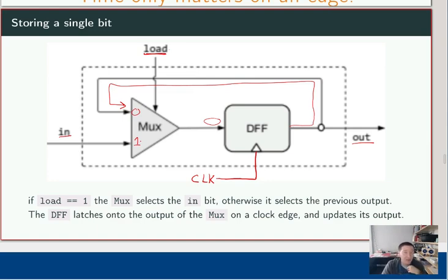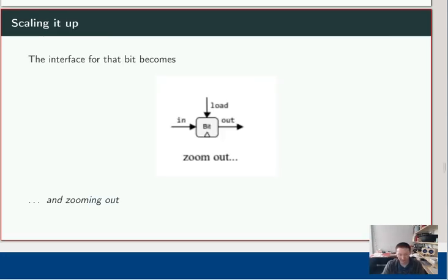Typically, you don't want to do feedback ever in a combinational logic circuit. That's a bad idea. But we are showing how we can use this recursive feedback idea to either support what we currently have and keep holding on to and maintaining a value, or we can load in a new value. And that's led us now to store a single bit of data. Super cool. That's not too bad at all. Once we can do this, everything's going to start building up on storing a single bit. So if this is that circuit we just designed, a single bit has the input, has the output, and then the load signal. Are we loading a new value, or are we maintaining the current value?